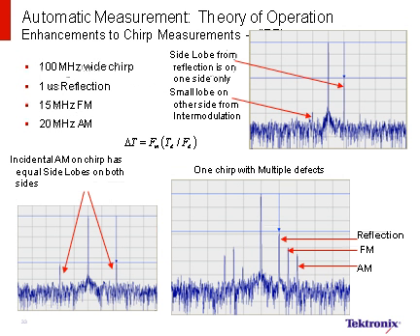It's important to note that internal mismatches are not the only phenomena that can be seen. Other distortions or incidental modulations, such as cross-coupling, can be represented. These may be difficult or impossible to see using common FFT analysis methods using spectrum analyzers, as the minimum time resolution of an FFT is the time occupied by the entire frame of the digitized samples used by the FFT. These things, such as incidental AM and FM modulation, can often be unique identifiers of a specific radar and be used to classify that type of radar.